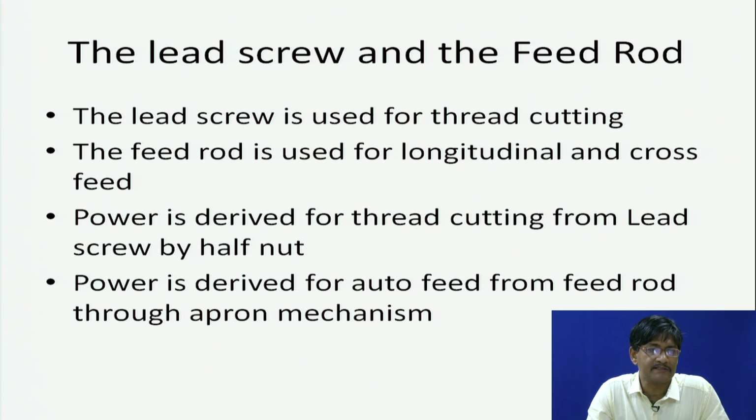In some lathes, in order to save money, sometimes they use the same shaft. Okay, the same shaft is used as the feed rod and the lead screw, that is, they cut a thread on a shaft, they also cut a keyway which is used both as feed rod and lead screw.